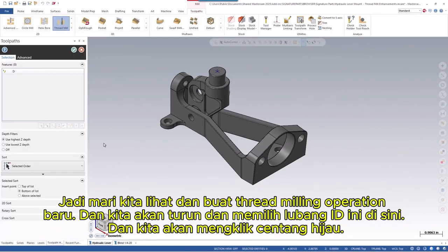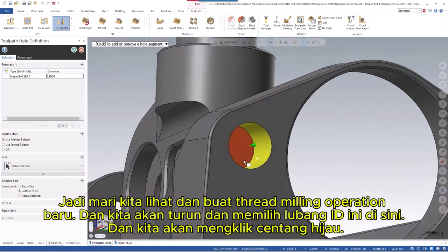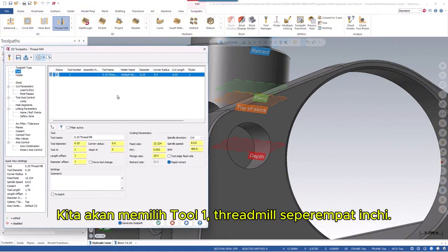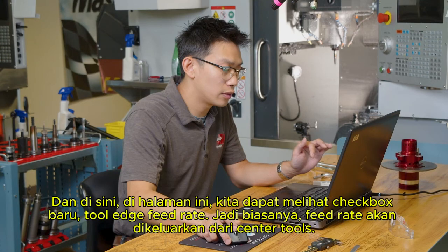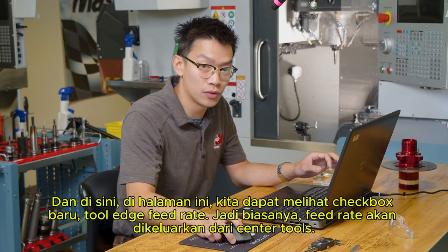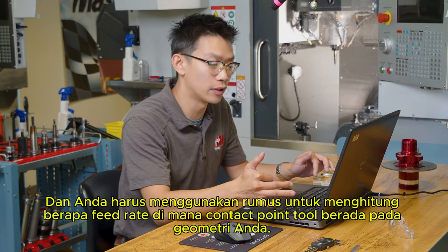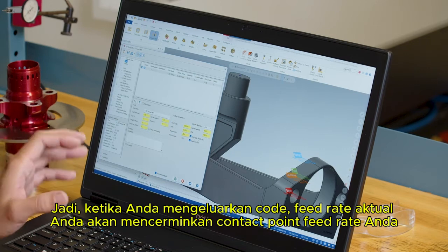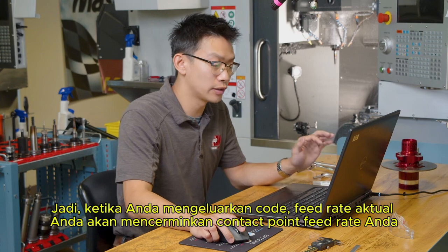So let's go through and create a new thread milling operation, and we'll go down and select this ID hole here, and we'll click the green check. We'll choose tool 1 1/4 inch thread mill, and here on this page we can see a new checkbox, the tool edge feed rate. So normally the feed rate would be output from the center of the tool, and you'd have to use a formula to calculate what the feed rate is where the contact point of the tool is to your geometry. Now we added this checkbox to automatically do this for you, so when you output your code, your actual feed rate would be reflecting your contact point feed rate.